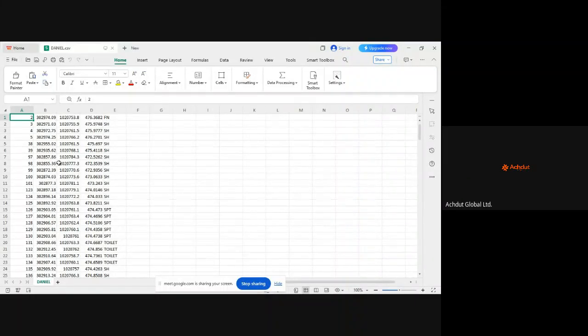This is a topo. You need these designs when you're carrying out a topo survey and you want to interpret what you have done on site. For your topo survey, unlike the four corners we just did on AutoCAD, you have your X, your Y, and your Z data. That means you have your eastings, your northings, and your height data. Your height data is what will enable us to plot a 3D design. So we have XYZ.